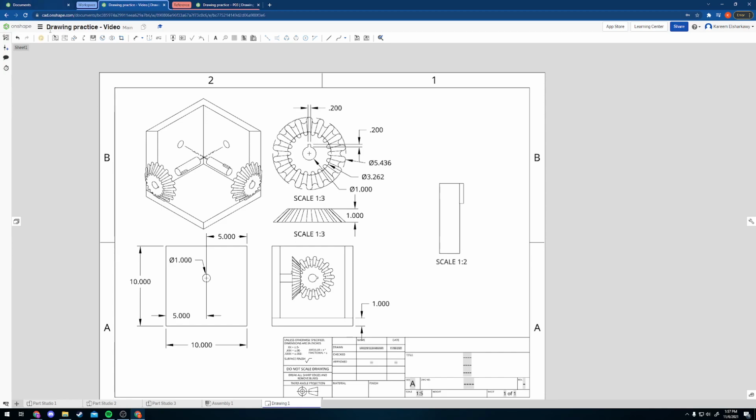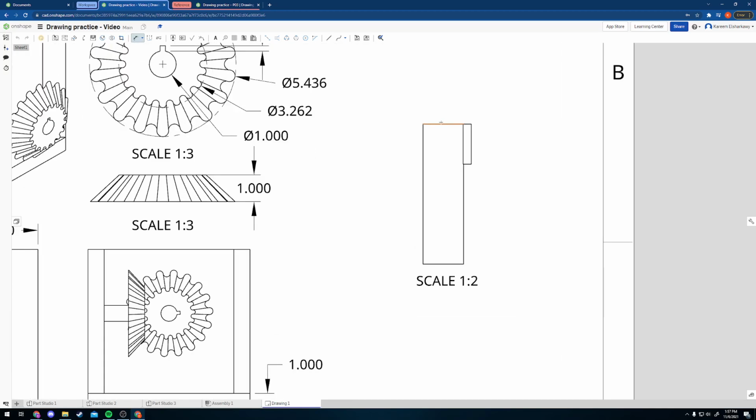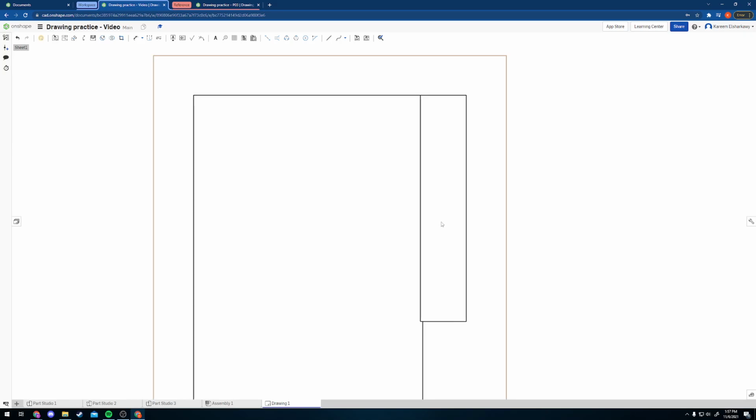I'm going to press escape to deselect the project tool, but now I want you to just select your dimension tool. Almost done here. And I'm going to hover over our line. You can see it's showing the dimension we want to show, the diameter, or almost the dimension we want. See, that's one thing you have to be careful about, because we know this is 1 inch, but it's not showing 1 inch because it's a little hard to see, but it's kind of cut off by the little tip of this notch here.